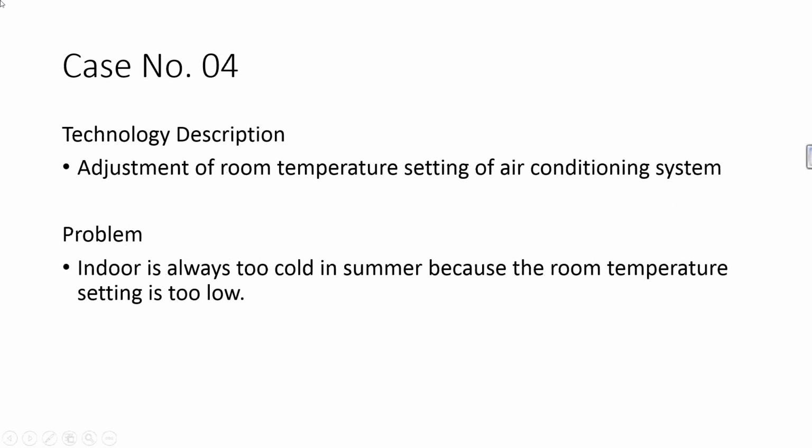Okay, case number 4. Adjustment of room temperature setting of air conditioning system. The problem is that indoor is always too cold in summer because the room temperature setting is too low.